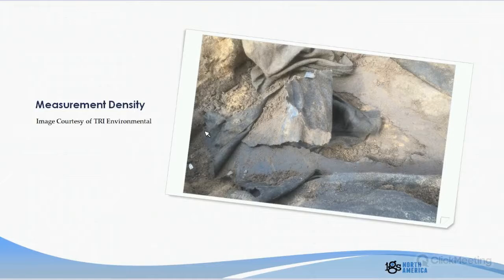The site was perfectly isolated, and well, it had a couple issues because it was a really wet site. But we had poor sensitivity, but we just passed the leak detection distance test for a 5 by 5 grid. It's a fairly large site, 18 acres, and so we did the entire first half of the survey at a 5 by 5 grid. So that should have taken 1 day, and it took 3 or 4 days. By the time we got to the middle, we found 2 really significant locations of damage. This is one of them in the photo.